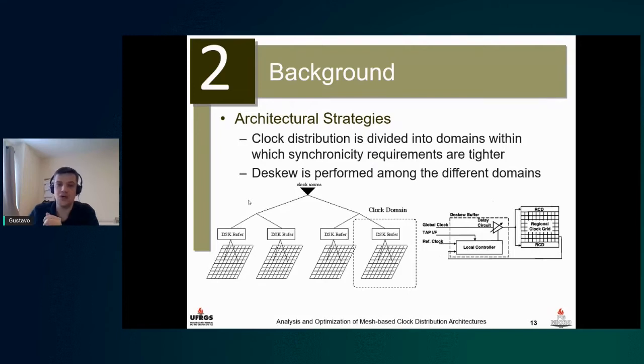It depends on what the timing constraints for the block are. At the root of each one of those blocks, we may perform a technique which is inserting the skew buffer, which is a buffer with a tunable delay that can be used to compensate for process variability. After the chip is fabricated, the skew buffer is tuned to make sure that the delays at each one of those clock roots is equalized.